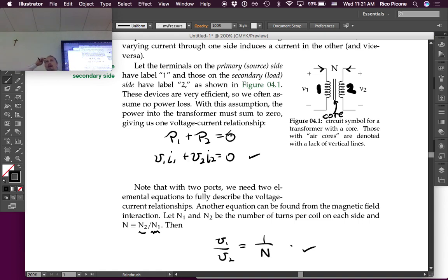So with power transmission over long distances, the resistance of the wire used starts to become important. And if you have long distances of wire, you get more and more accumulation of this effective resistance and dissipation of power through that resistance.